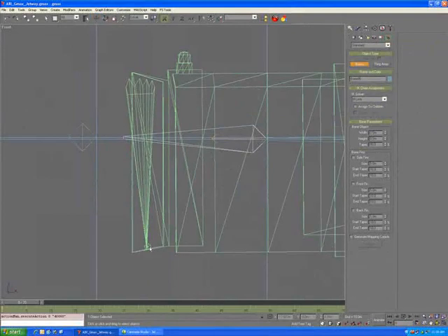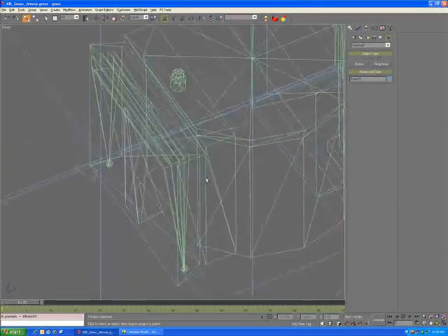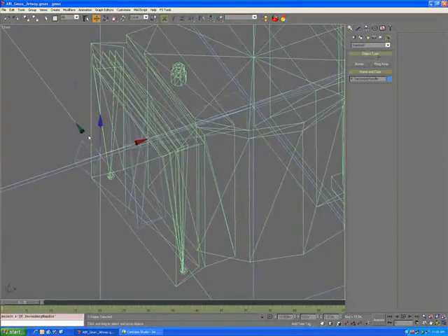Okay, so what I'm going to do now is I'm going to create 2 bones for the Jetway hood. One at the back of the hood, and then one at the front of the hood. And we'll move this one up just a little bit here. There we go, so that it lines up a little better. We're going to link these bones to that bone there. That way, if this IK handle moves, they will follow along.